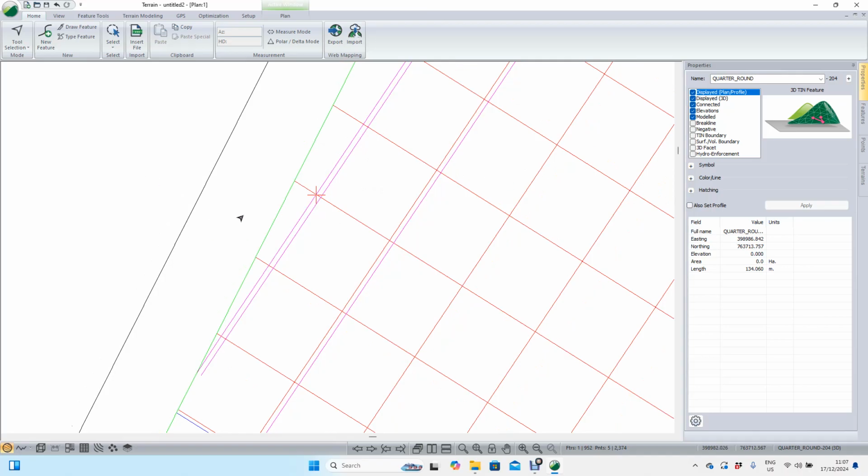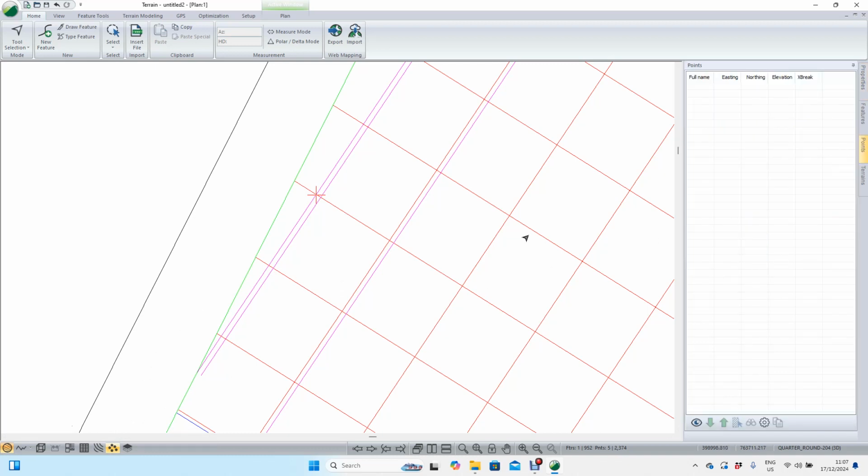If you want to see all those coordinates, it's pretty straightforward. You can either select this button down the bottom called Points, or there's the same tab along here called Points. Then if we select this line that we've been working on, this one here, and click the little display icon at the bottom there, you can see it's now showing you all the coordinates along that line. If we snap on a coordinate, it shows you in the plan view here where that coordinate is.